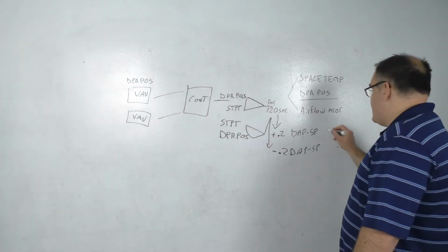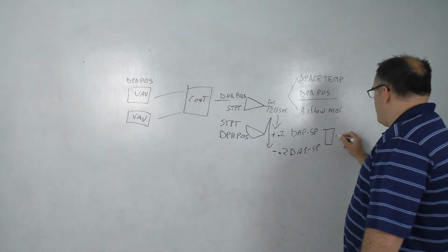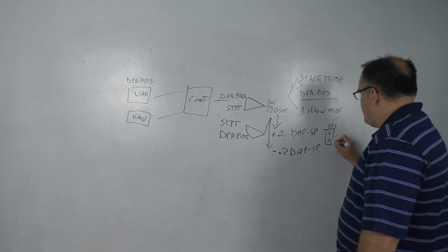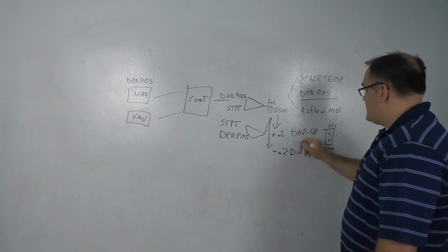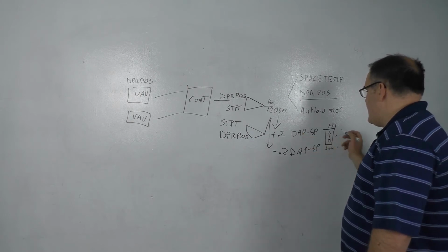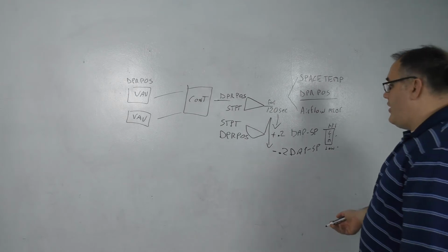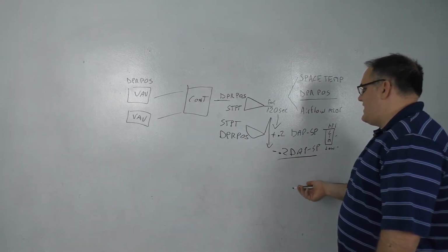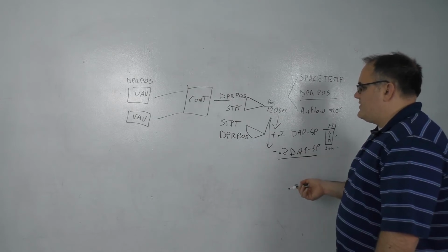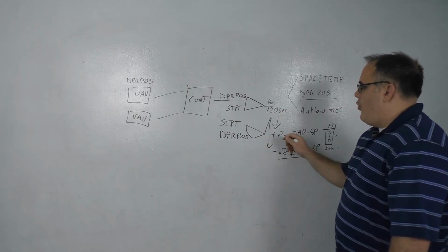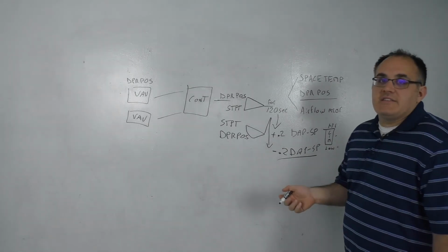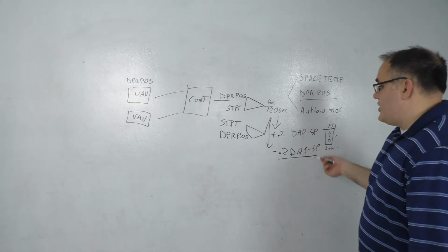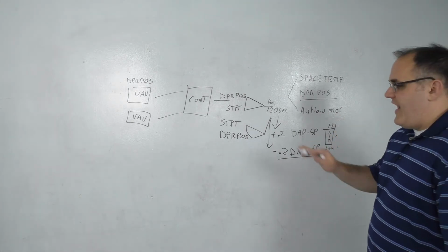And then both of these right here would go into a limiter that limits the high and the low so that these don't cause an issue. Although you could also just say, hey, I'm going to disable this when the calculated set point drops below a certain discharge air pressure set point value.